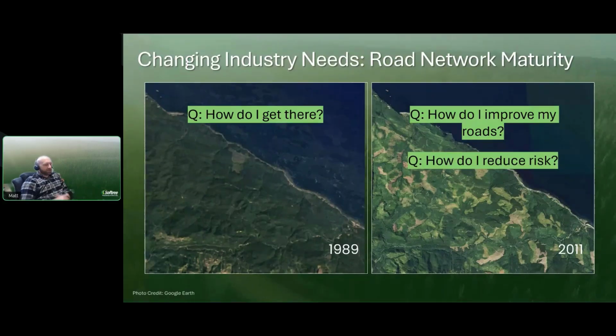So was it something that was built 20, 30, 40 years ago on a steep slope that is basically just organics bladed over onto organics and waiting for it to settle and slough out and fail? Are there ditches that are going to block or culverts that are blocked, and we could end up with washouts at undesirable times or contribute to something more dramatic like some of those landslides that we looked at previously?